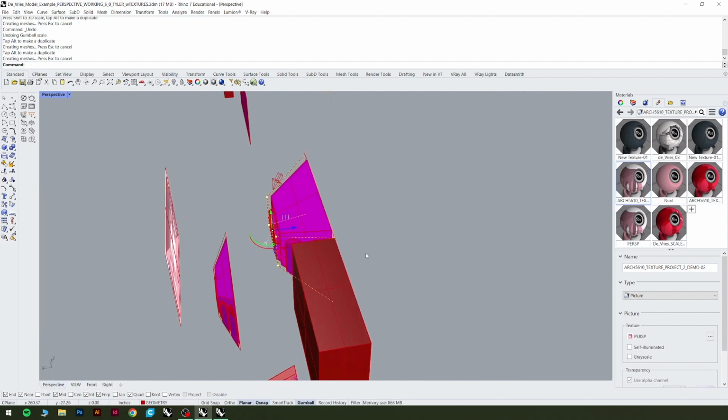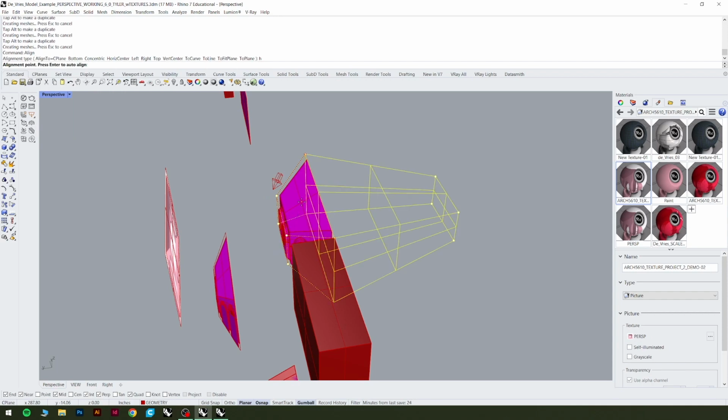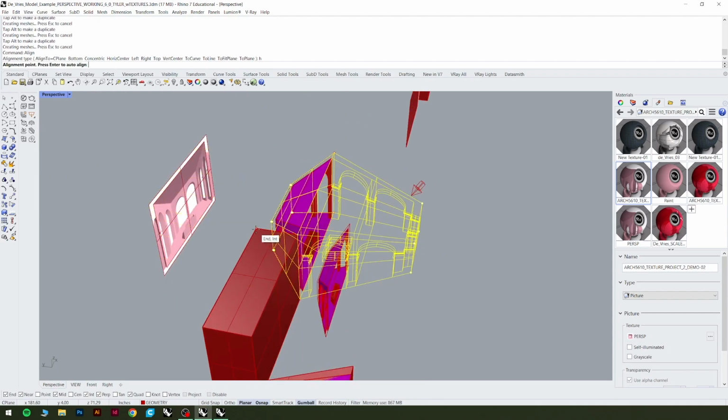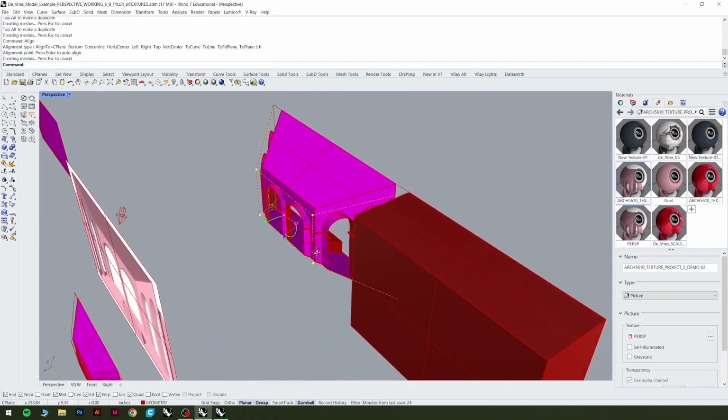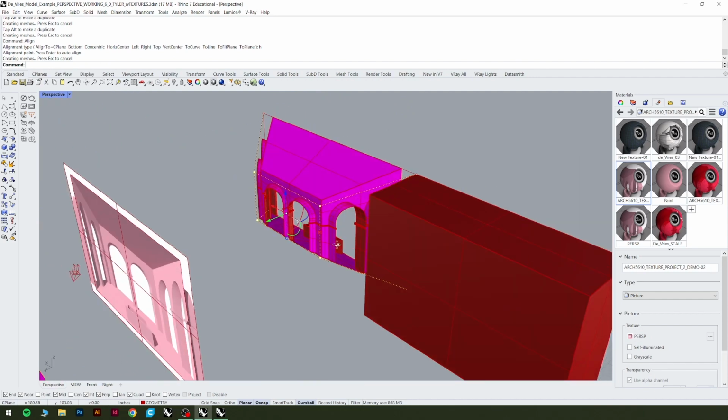But so rather than sloppily trying to eyeball this and moving it until I feel like it's 4 inches deep, I'm actually going to type in align, and I'm going to hit H, and it could have been V because I really always forget whether it's horizontal or vertical. But yeah, so that was the align command. Horizontal center is what the H shortcut takes you to, and then I can just object snap to the corner of that 4-inch deep bounding box, and then we're good.